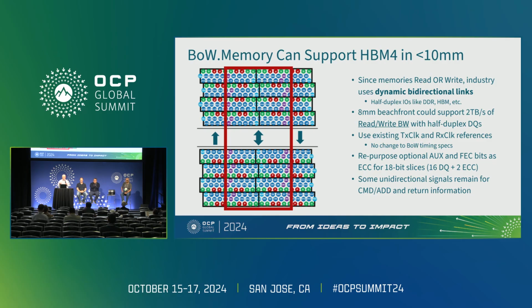The other thing about memory, memory's not binary. It doesn't want to have an 8-bit or 16-bit interface. It always has ECC and other things on top of it. And a bunch of wires happens to have some additional optional pins that we can repurpose as ECC bits, make a by 18 slice instead of a by 16. And it works quite well for the applications we need here.